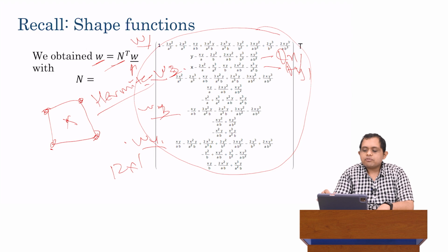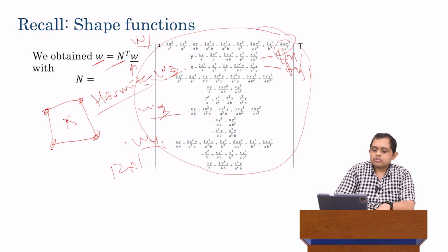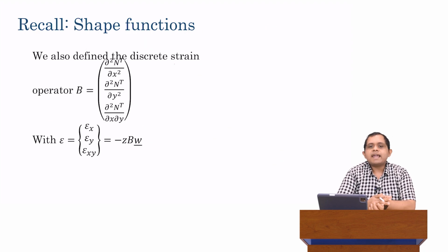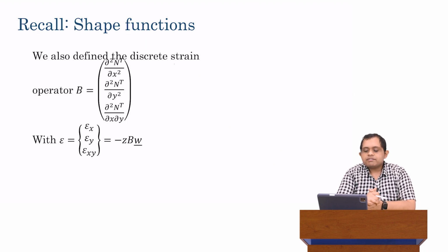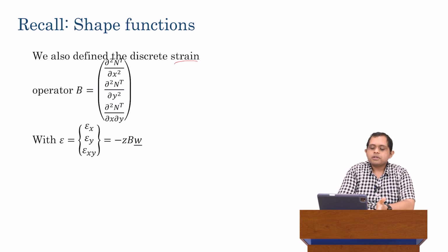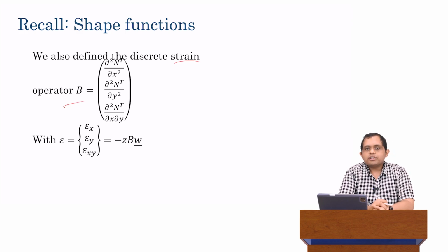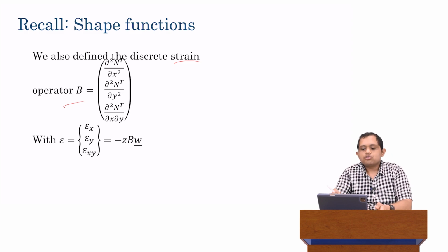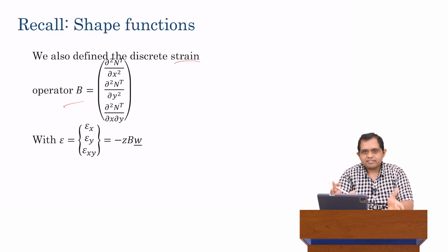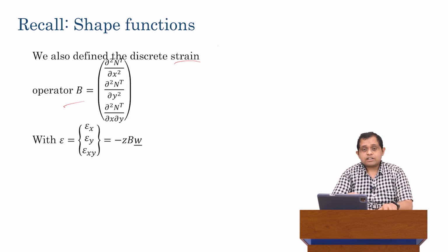You will also note that each of the shape functions was fourth order. That's going to be useful because, as we look forward towards the end of the last lecture, what we left on was this discrete strain operator. What we don't care too much about is the degrees of freedom, those are fine. What we're actually interested in is stresses, and before stresses, we're interested in strains. So it's fine if we can express the displacements using degrees of freedom and an interpolation. We would actually like an interpolation that gives us the strains. That's how we start off with our analysis.